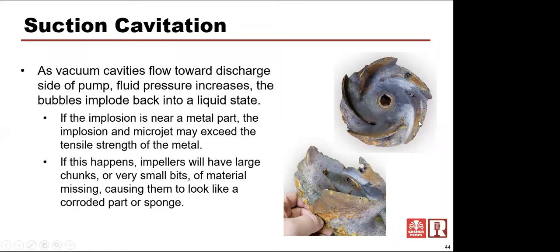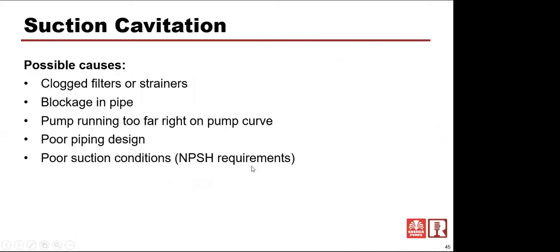And that's why you're seeing this being torn away right here. And I have seen impellers that look much worse than this, much more significant. This actually, because of the amount of corrosion or erosion out here on the side, looks like we may at times be having some recirculation cavitation, which is the next type of cavitation.